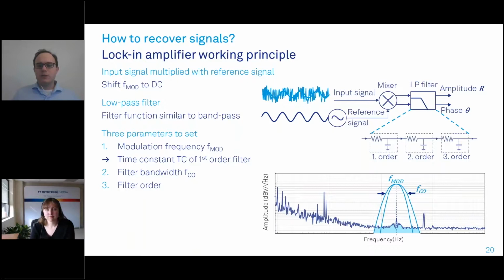So what you will do is use a slightly slower photodetector. Therefore, the photocurrent from the laser photons impinging on the photodiode will be slightly smeared out, and you will see basically the response function of your photodiode. But the integral of this short pulse will be precisely proportional to the intensity of your laser pulse, and this is why it works.